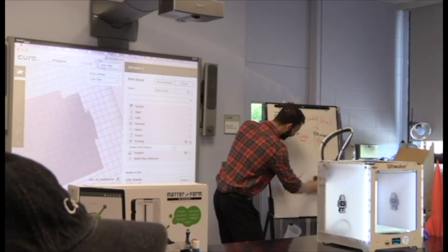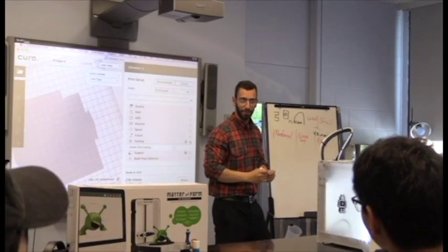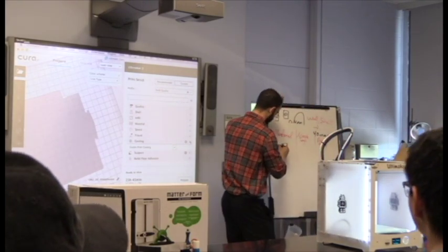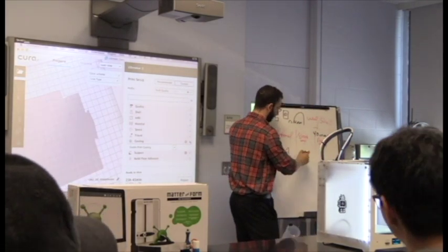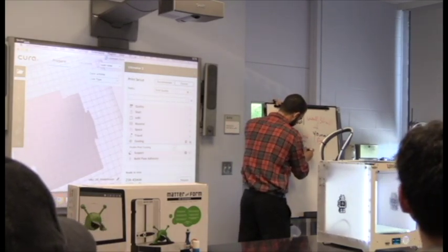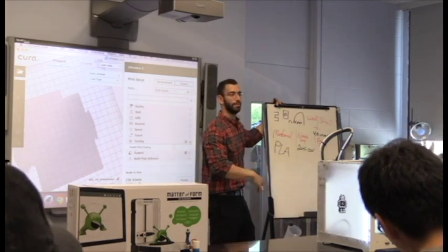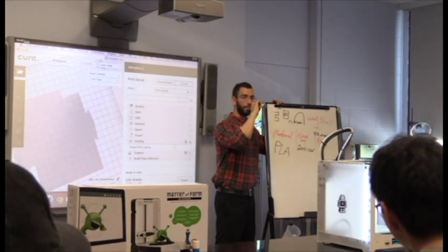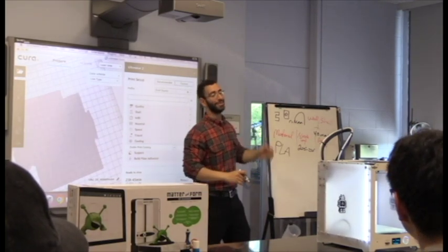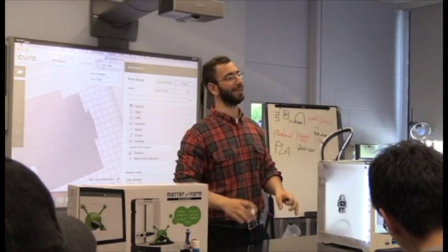Okay, this is usually PLA, which is the coldest material we'll be working with. Okay, PLA is kind of like the easiest, coldest material. The nozzle temperature is between 205 to 220 degrees Celsius. Okay, I'm not going to put Celsius. We always work in Celsius. Okay, metric, SI system. 200 degrees Celsius. You do not want to touch that. Okay, it'll burn you before you even know it.